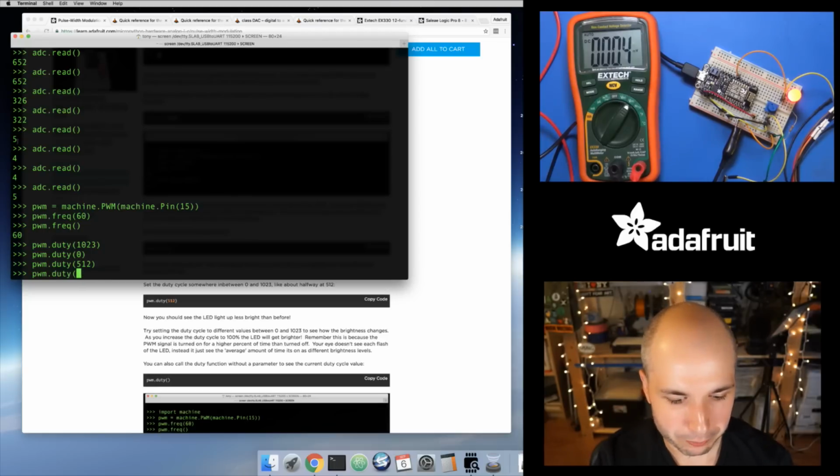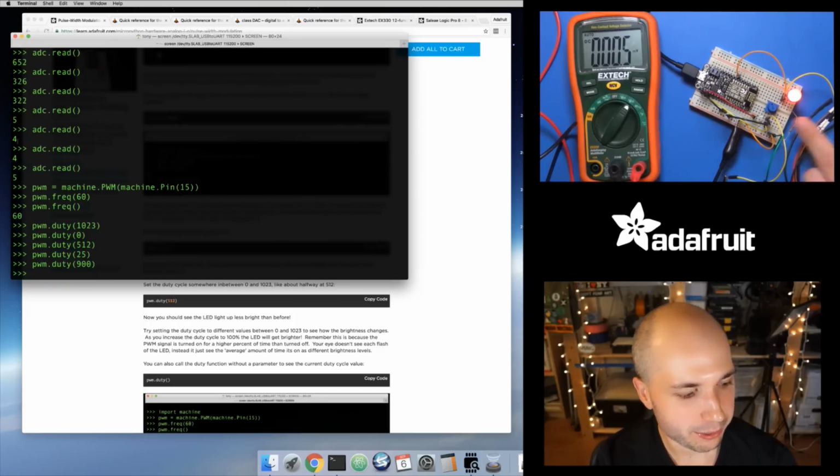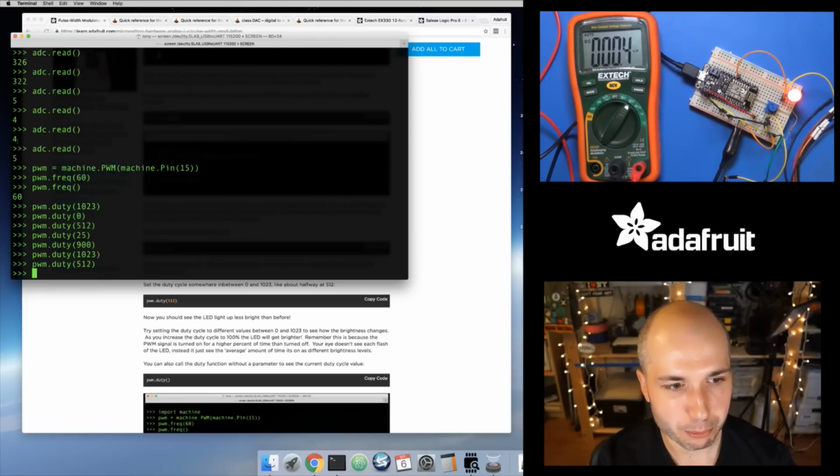Let's go down to a smaller value, like how about 25. Okay, so you can tell it's definitely noticeably dim in this case. It's turned on, but just barely. And then if I go up to maybe 900, something a lot higher, it gets pretty bright. And then maybe let's go back to the full value, 1023. You can't even tell, but it's maybe a teeny bit brighter in that case. So okay, let's go back to the halfway, pwm.duty 512. Okay, so let's look at what this duty cycle thing means.